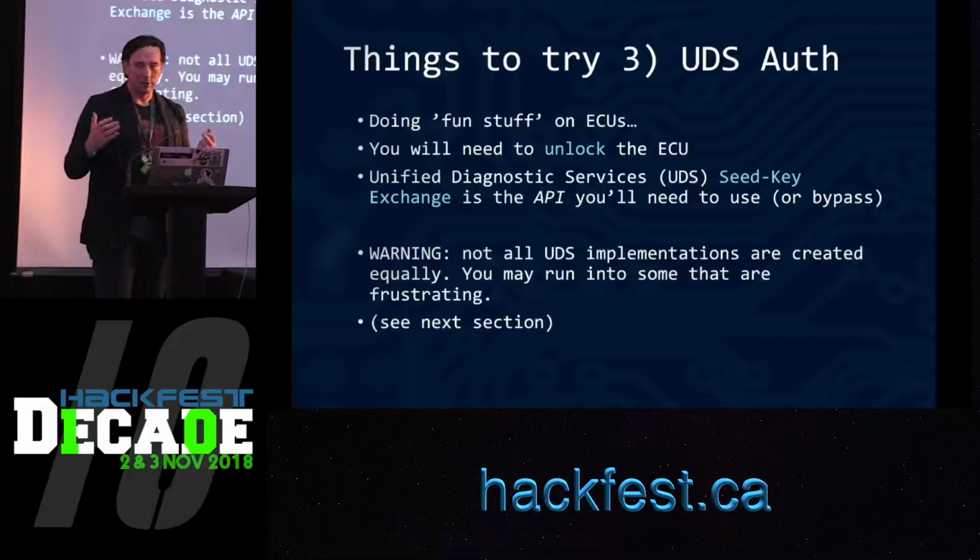And with Radare, you can open multiple files. So if you had this weird firmware that came in multiple segments, you could have one of these config files and save the multiple segment files as individual files. You wouldn't have to use DD to put them together a weird way. You could just put them into the virtual address space using this config file, right? You set up VA. IOVA is all about virtual addressing. You're going to want that because remember, we're doing weird segmentation with the files.